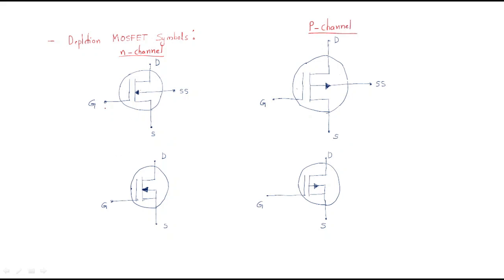Look here, we have the gate first, and we have the source terminal and the drain terminal, and in between we have the channel. So this is the n channel type. This is the n and the body is the p. It's always like a diode, p and n combined together, that's why the arrow mark is like this.